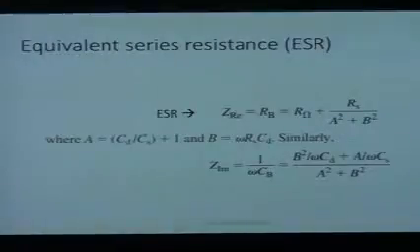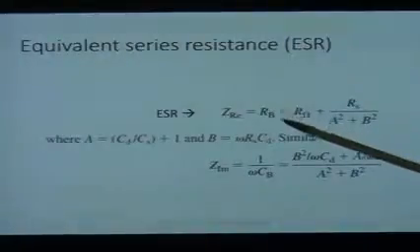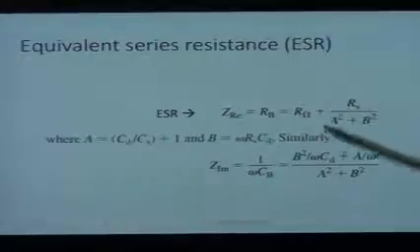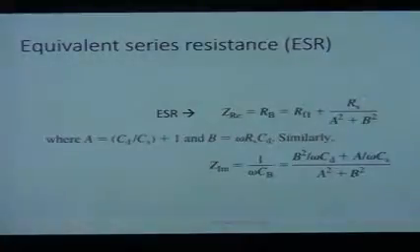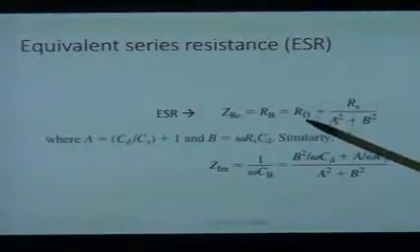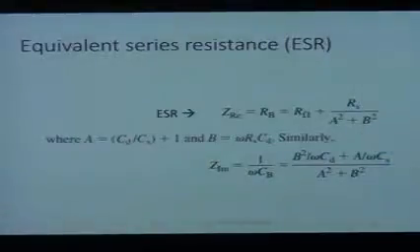Okay, so mainly what you do is extract the equivalent series resistance. However, if you want to relate those terms back to what we had on the last slide, you can do it. The way you do it is that the equivalent series resistance is a combination of that solution resistance that we had and the pseudocapacitive resistance.